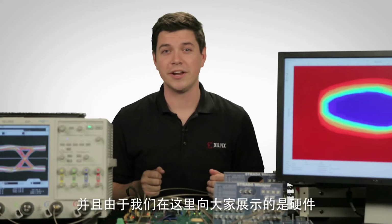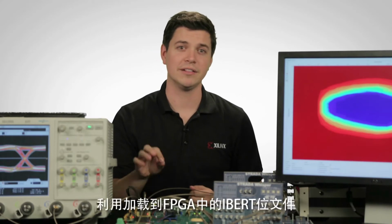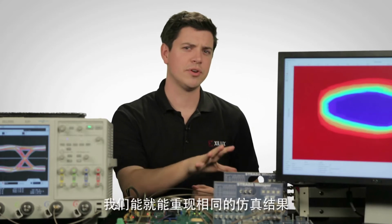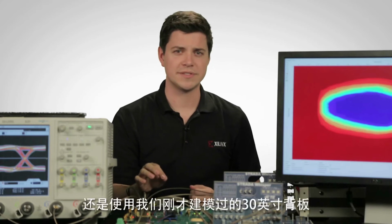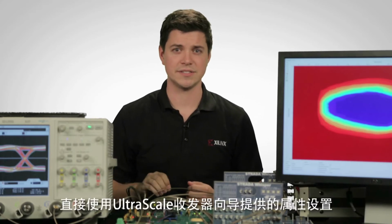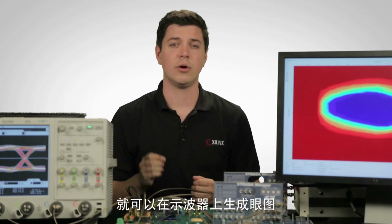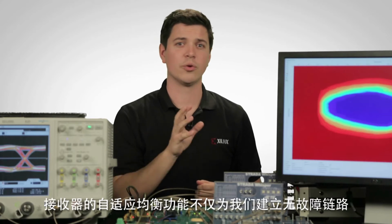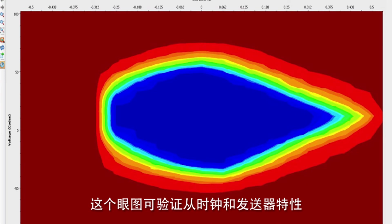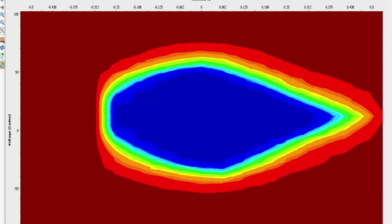And since it's hardware we're here to show you, we can reproduce those same simulation results using an IBERT bit file loaded into the FPGA with the Vivado serial I/O analyzer. Using the same 30-inch backplane we just modeled for, attribute settings sourced directly from the UltraScale transceiver wizard, and the same pre- and post-emphasis settings used to generate the eye on the scope, the receiver's auto-adapting equalization is giving us not only an error-free link, but an incredible amount of margin. This eye validates the entire transceiver, from clocking and transmitter features through the receiver CDR and auto-adapting equalization circuits.